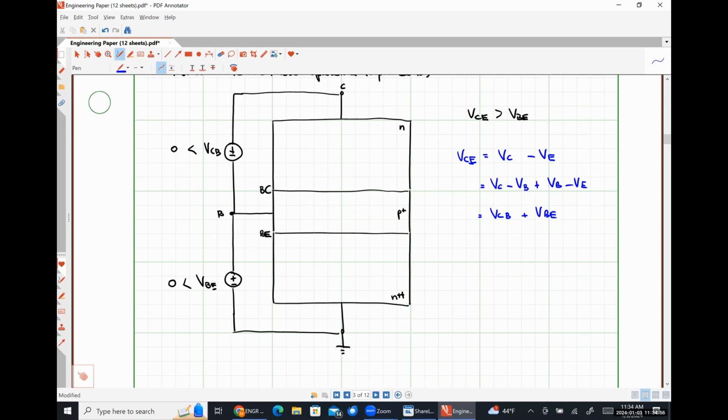All right, so these biasing conditions mean that the barrier potential across the base emitter junction is lowered, which is going to yield a small electric field in the up direction. So this side is very heavily doped, so I'm going to draw the width of the depletion region very thin. And then this side, the P side, is more lightly doped, so this side's going to be wider. So we have here bound positive charge, and here bound negative charge. Actually, I got that backwards.